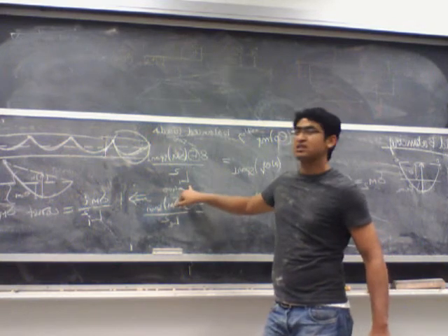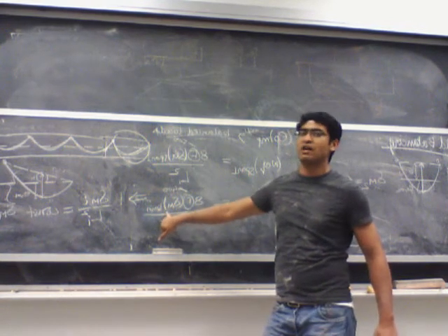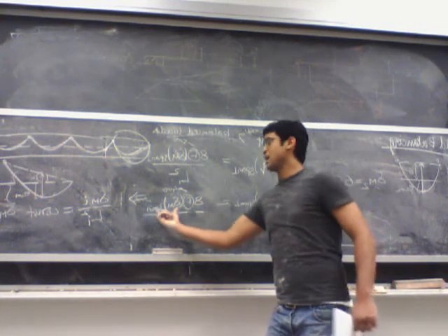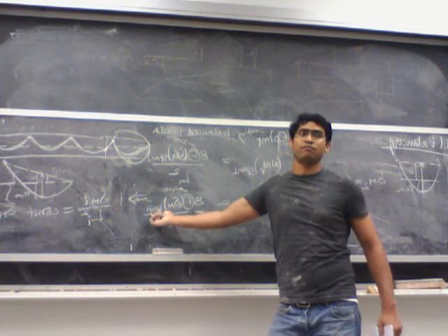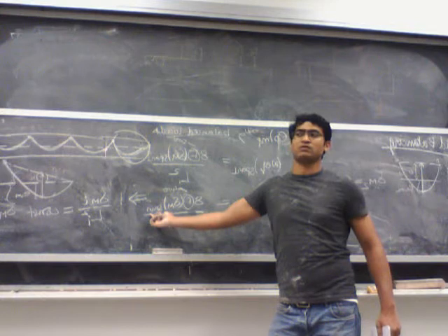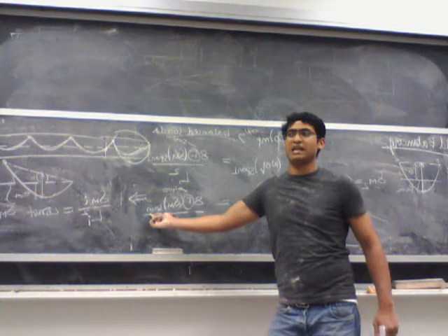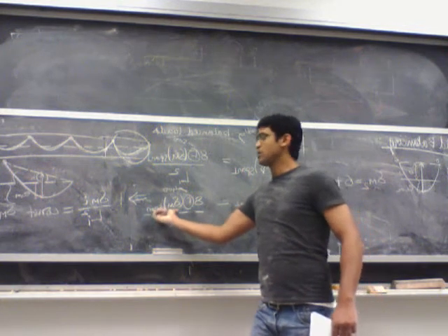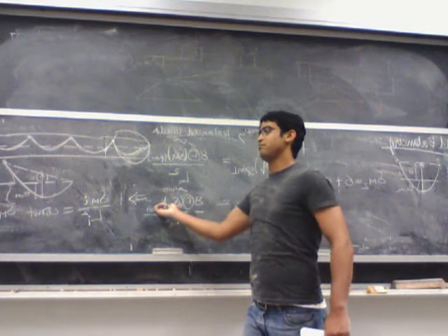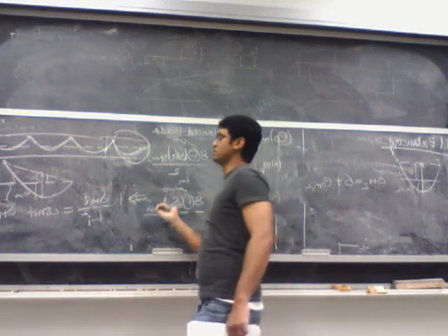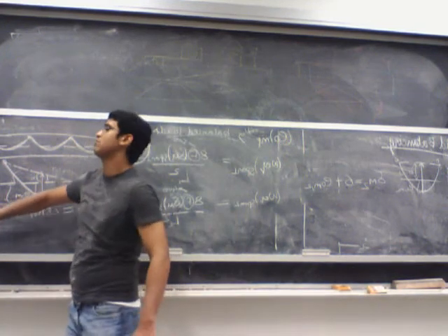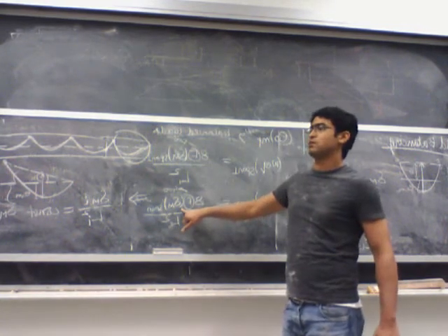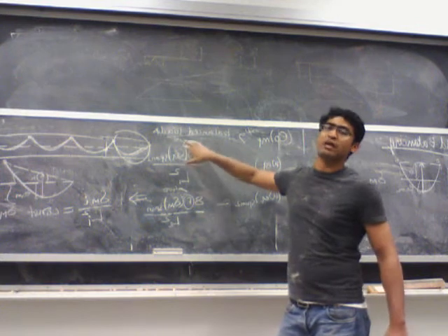That means if I increase this value of f for this second span, I'll decrease the value of delta m, right? Because the product is constant. Am I allowed to decrease the value of delta m? No, it's not. The tendon profile is not fixed yet. You are trying to find out what the tendon profile is. But are you allowed to decrease this delta m, or are you allowed to increase this delta m? Decrease. You are only allowed to decrease it because this delta m currently is assuming the maximum possible E naught. So since you cannot increase your E naught, you cannot increase your delta M. So what you do is you pick the larger value of the F that you get from all the spans.